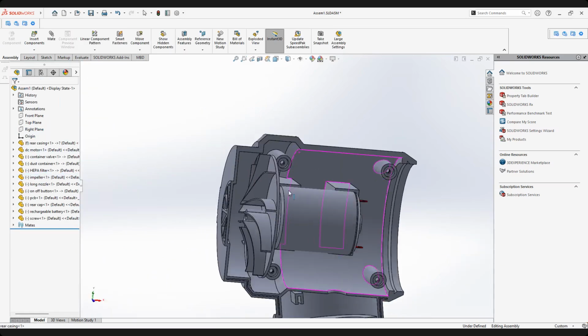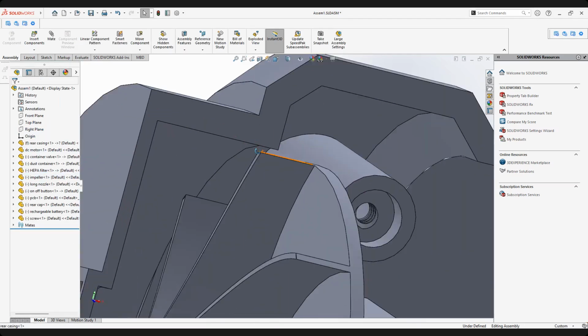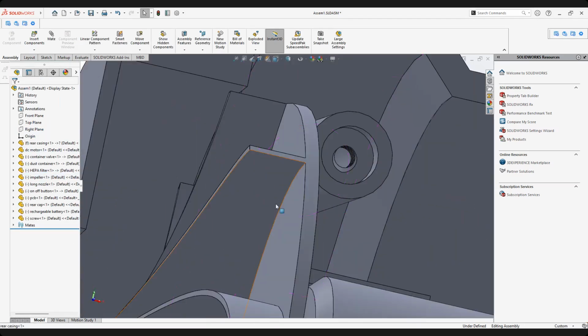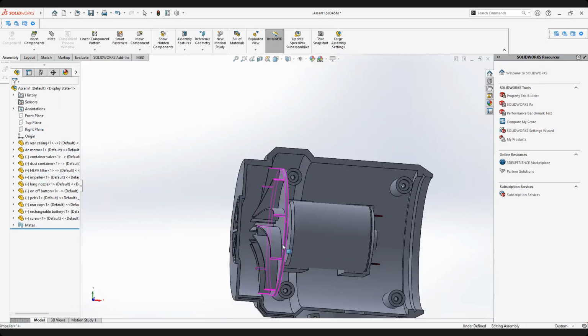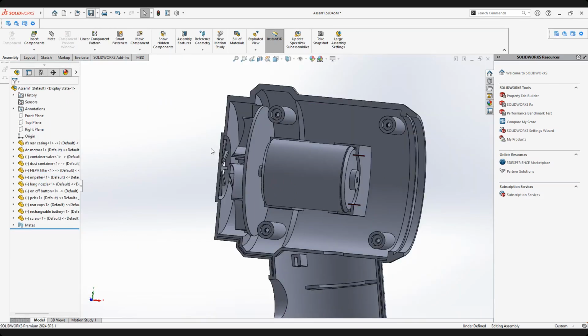Okay, there is no interference. You must check your assembly. Make sure there is no overlap. If there is overlap, where it touches any internal part, you have to do an adjustment in your part modeling, right? I already did this, no overlap. Okay, I save my file again.